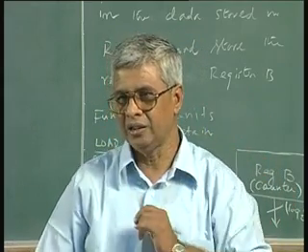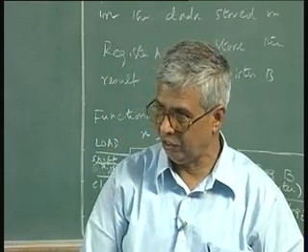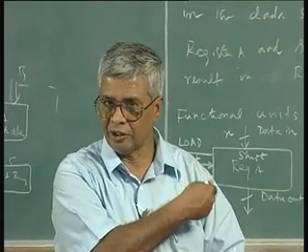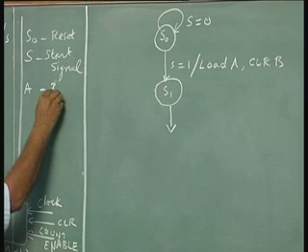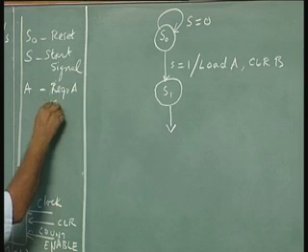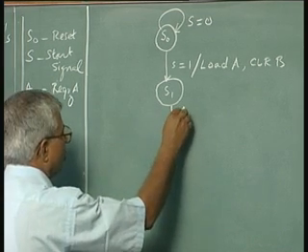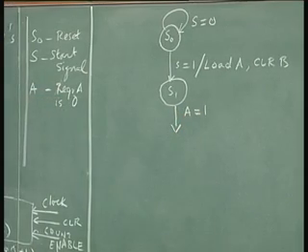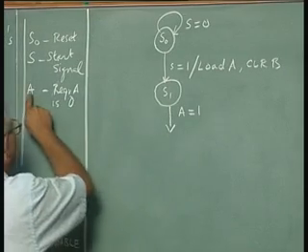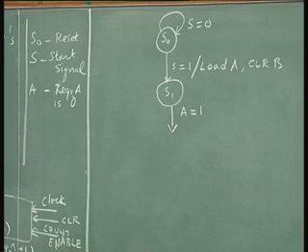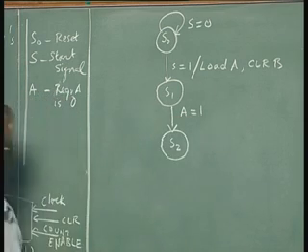So, I am going to call a signal A. Signal A is a signal which will become 1 when the value of the register is 0. So, it is a signal I am defining. All these things I should account for in the architecture, the functional units. So, A is a signal which gives you the content of register A is 0. So, if A is 1, that means I have either completed the operation or there is nothing to count, either way. A is the value of the register A. In that case I go to S2 state. So, I am ready to go to reset and load the next value, but